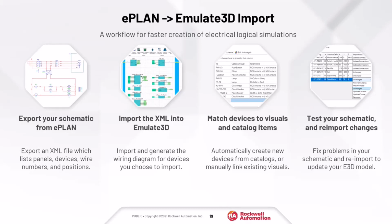You can physically connect a PLC 1756 rack with the controller, the I/O, and everything like that to a laptop, and that laptop and the PLC will then drive the simulation environment. In the simulation environment, you can interact with the model. You can press a start button here, a stop button here, and it will give feedback directly to the PLC and back to validate your PLC code. It's a really, really cool tool.